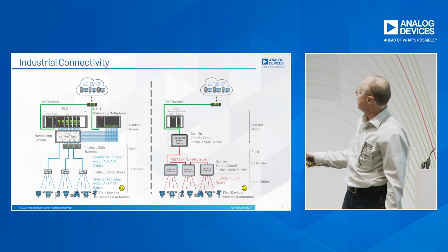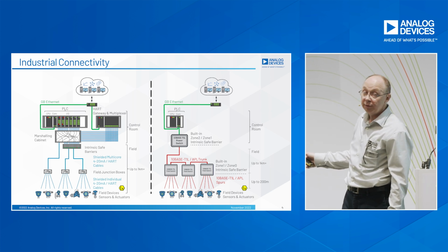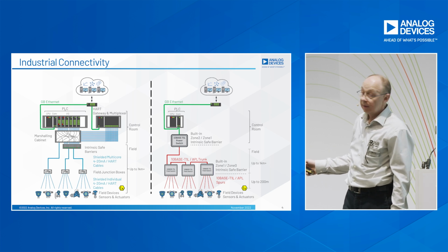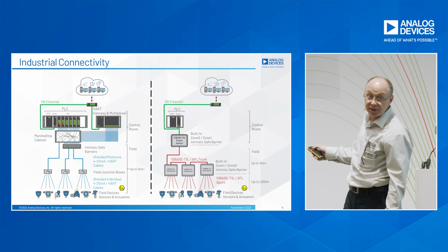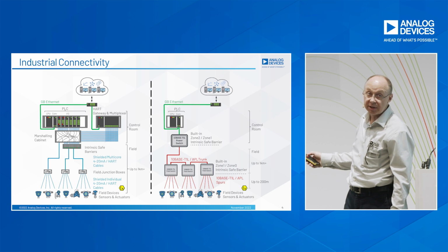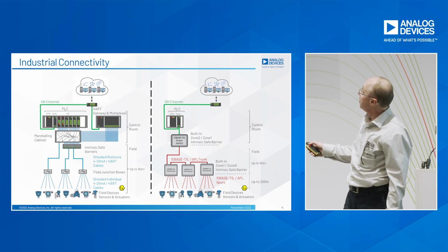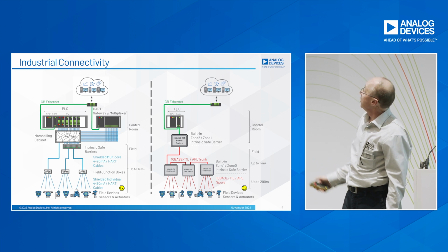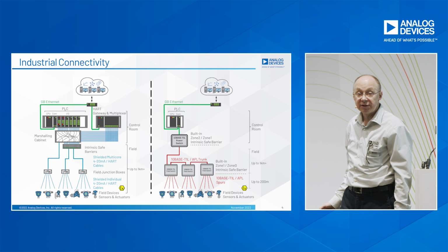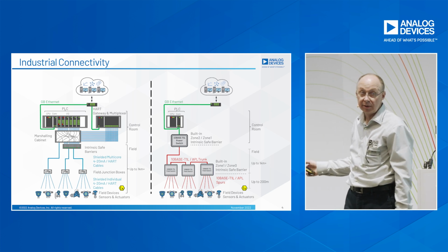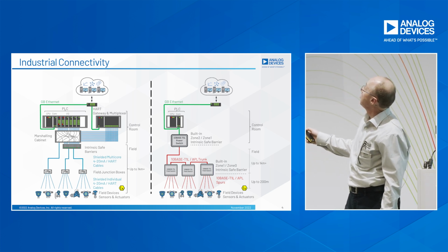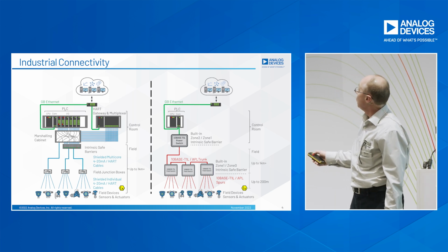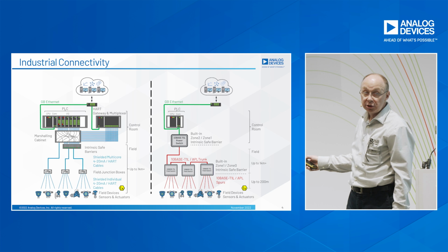You have the same signals coming individually from the sensor, but they now come to a field switch through what they call spurs, up to 200 meters per the APL specification, and then you can chain the field switches and get the information up to what they call the power switch, for injecting the power to supply all the sensors, and to the PLC. And what that brings is an IP address on each sensor.